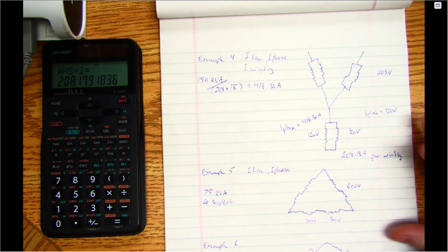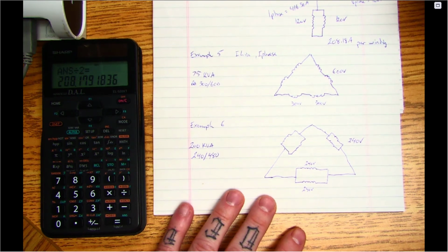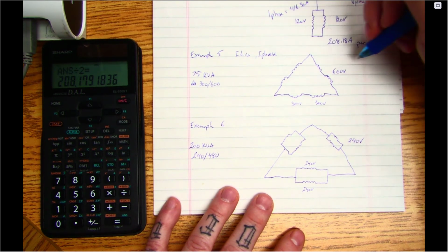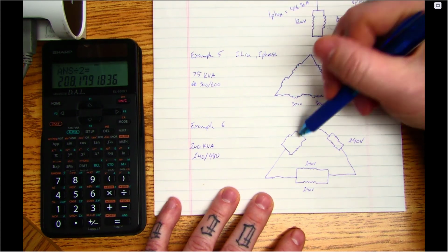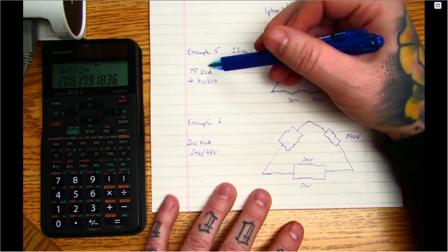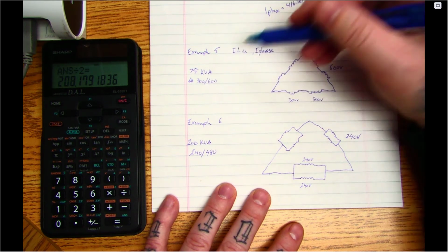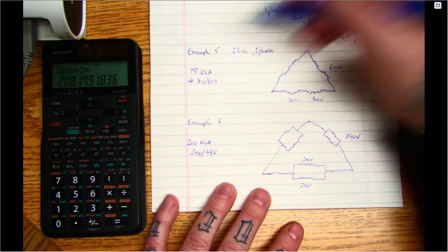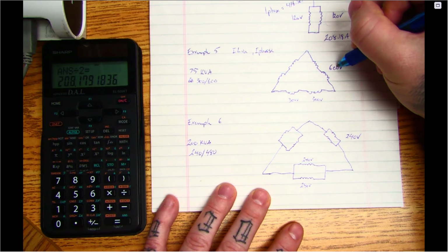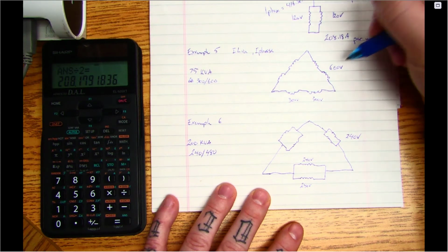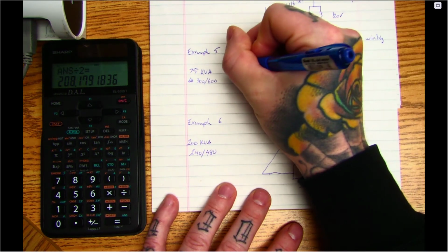Okay, so just some terminology there that's different, whether we're hooked up in Y or delta or series or parallel. If it's able to be hooked up in series or parallel, we would have two voltages, because you could hook them up for a higher or lower voltage connection. This example doesn't really show that, but it would be available if we have that option. This is saying we have a 600 volt phase voltage, so we have a 600 volt line, because this is a delta hookup.